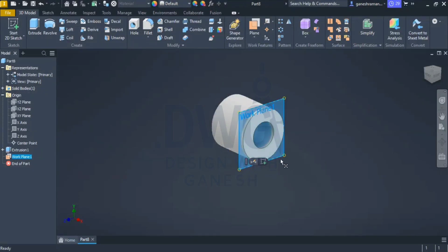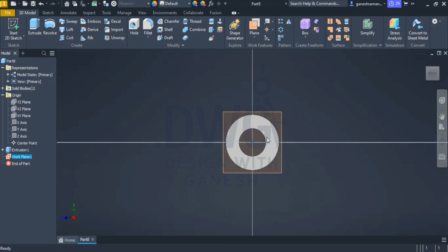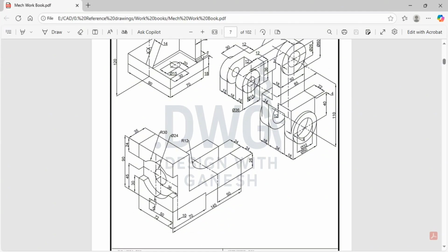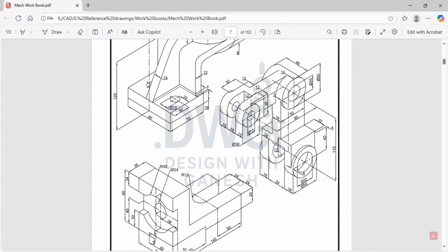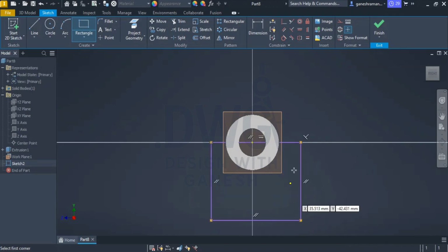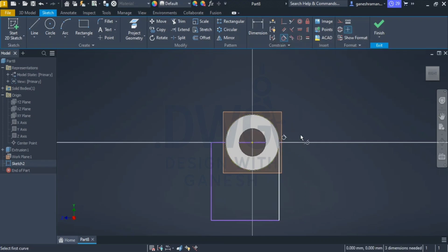Which is what is mentioned here. Okay, now click on this plane and add a sketch. Okay, now the sketch looks like this, so from this point to the bottom, which is 110 minus 40, it is around 70 plus 12. Okay, we will make it with the 70. Okay, so click on the rectangle and make sure of these, use the tangent. Here you can set the constraints and the tangent, select this outer surface and this one like this. Okay, so they are tangent.